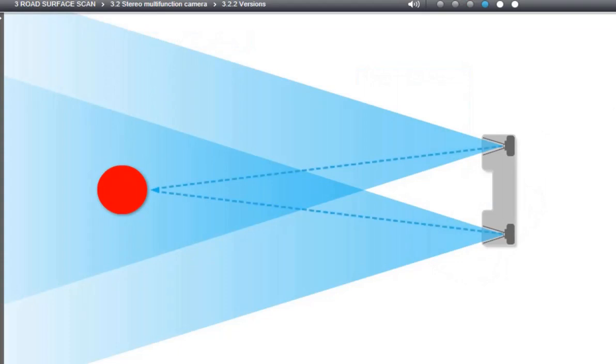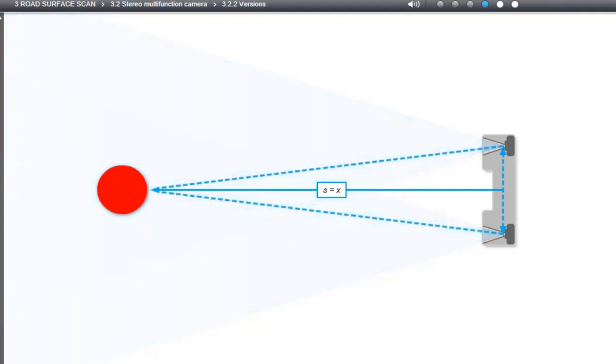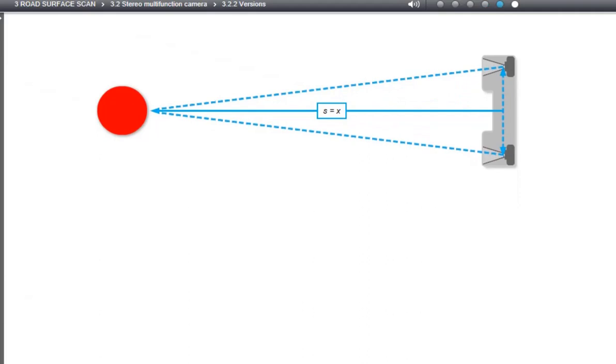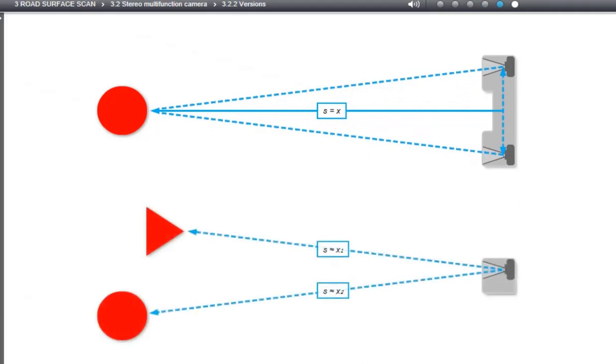The stereo camera can measure the distance to captured objects because it has two independent optical paths that are computed in conjunction with one another. In contrast, the mono camera can estimate the distance to captured objects only by comparing them against the environment.